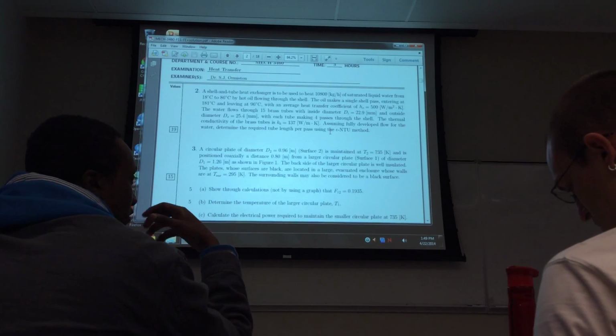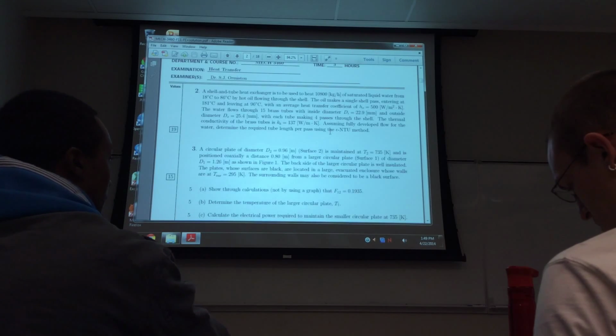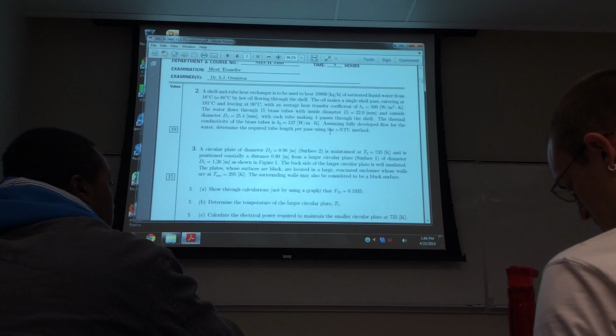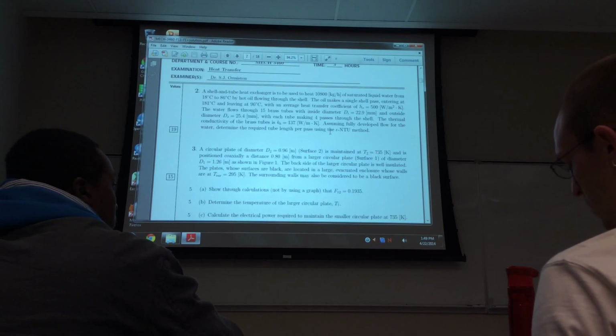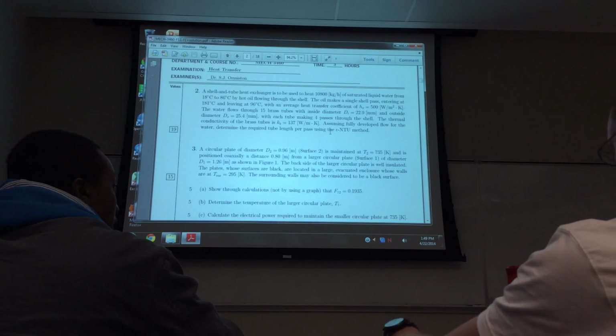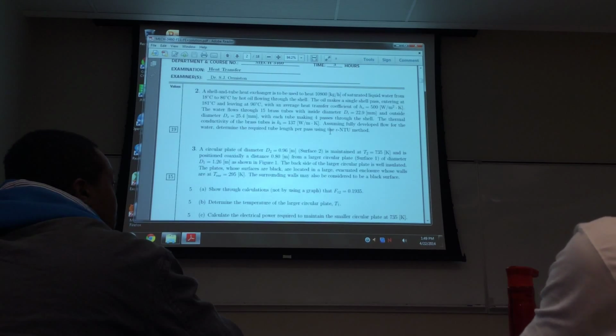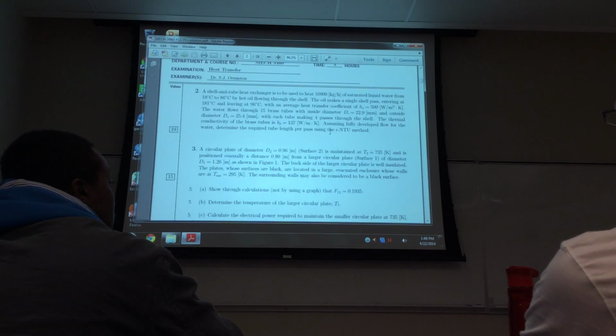Okay, well, we can look at the solutions that I had to derive if you want. But one good point to know is when do you choose an infinite fin or not. I think it's 2.65, isn't it? mL times L equals 2.65 or higher. That's an example in the textbook. So it can save you some time. There's no guarantee you'll use that this year, but if you calculate that just as a test to see can I use that equation, it simplifies things a lot. It has nothing to do with the derivation, it's just for a standard fin.